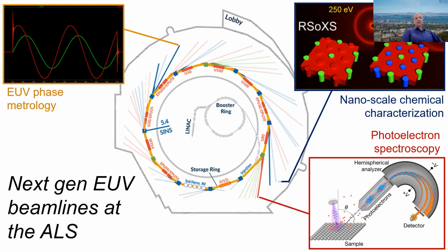So there's a new beamline that's been developed for that. And another unique thing about EUV lithography materials, even though EUV light goes into the film to record the image, it's not the EUV photons that do the work. The EUV photons generate some photoelectrons, and it's in fact those electrons that ultimately do the work.